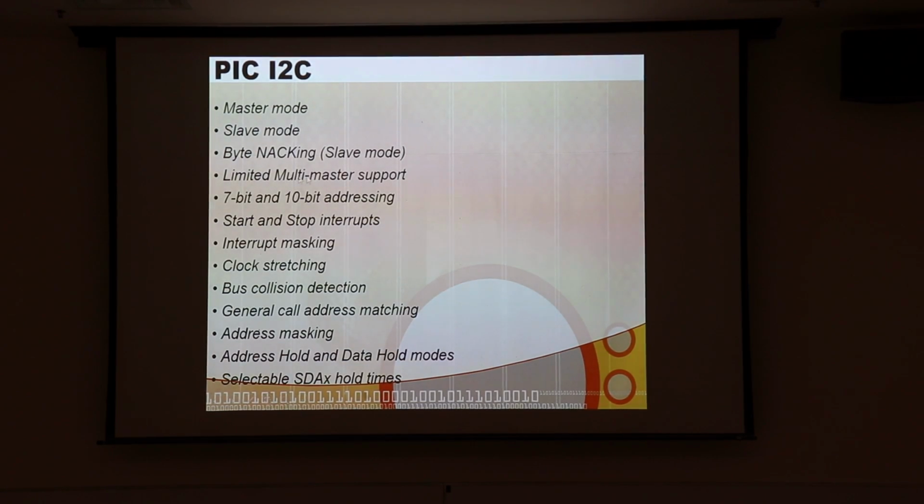There is multi-master support. It's sort of limited, but it's sufficient to make it work if it needed to. And then there is a 10-bit address mode, which I haven't actually seen used, but most devices that are set up for I2C use the 7-bit mode. It can also interrupt on stops and starts, so that helps you manage it if you want to set those interrupts up. It has the ability to support clock stretching.